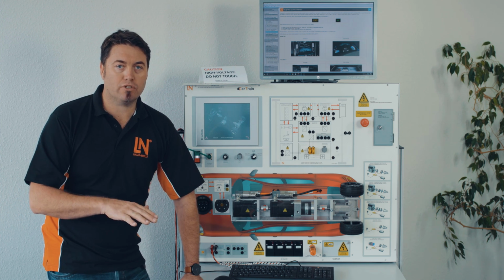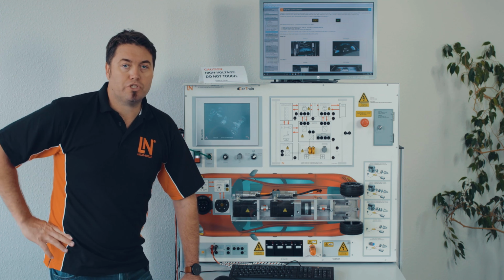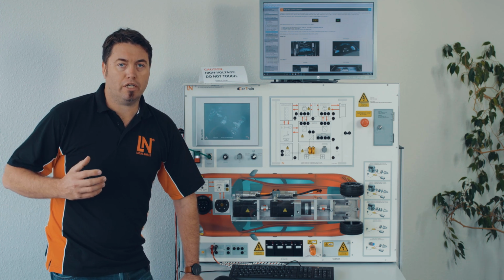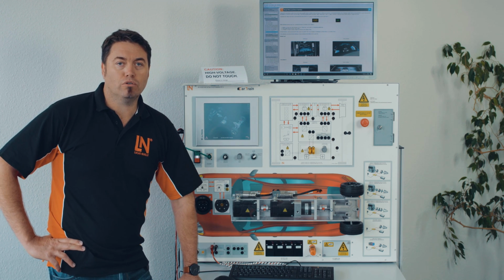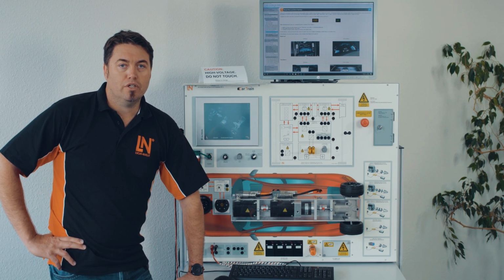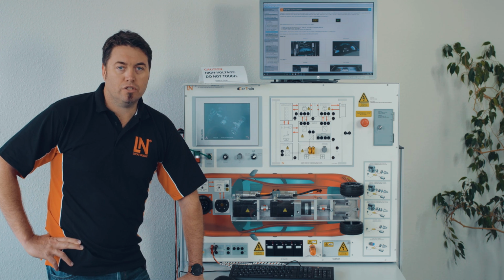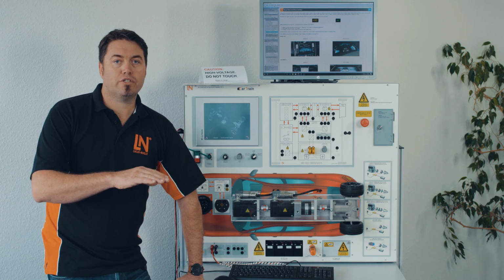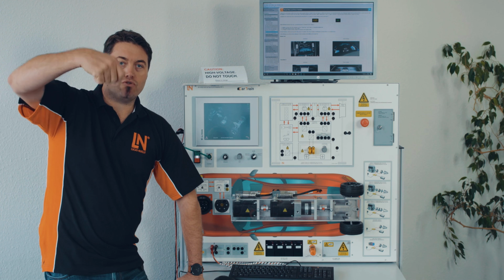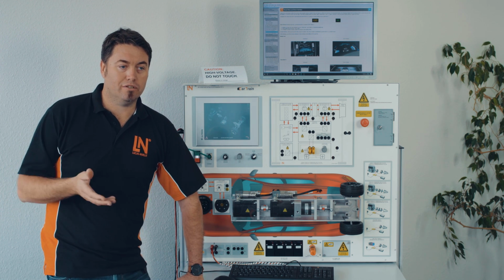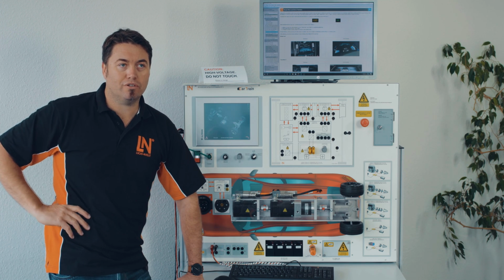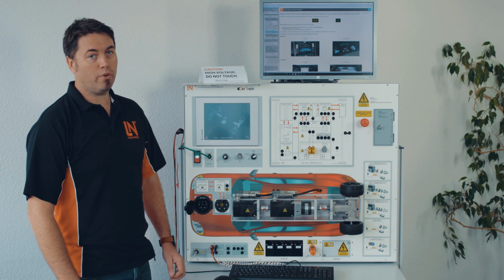When the battery level gets low, the combustion engine will start, trying to charge up the battery again. So you need to be very careful. There's the old urban story of the Prius technician who drove the vehicle onto the hoist, put the vehicle up in the air, drained the oil from the engine, and all of a sudden the engine started, without oil. So the vehicle is stuck up on the hoist. Very important for your students to understand that and be aware of the situation.